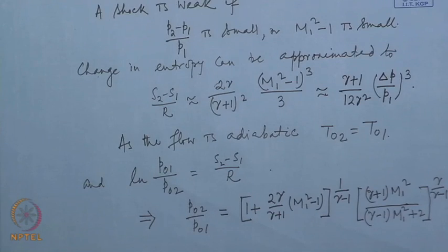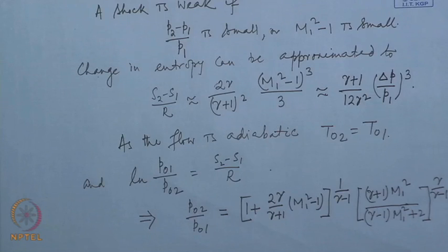And since we have used integral relationships at station 1 and station 2, any non-equilibrium region is possible between station 1 and 2. The only requirement is that the flow at station 1 and station 2 must be in equilibrium, and a non-equilibrium region may exist between station 1 and station 2.